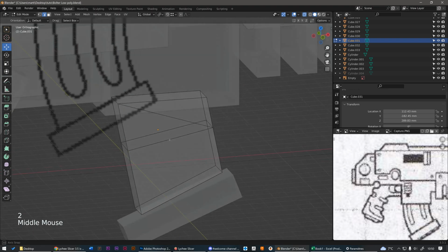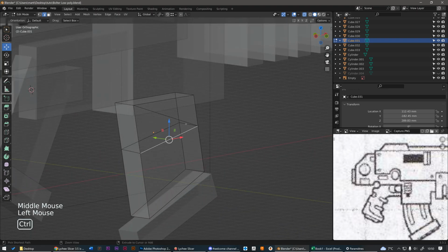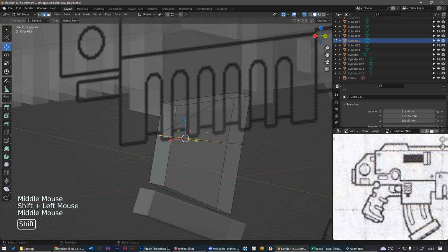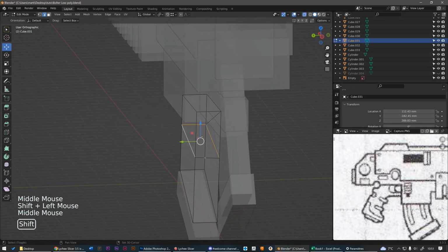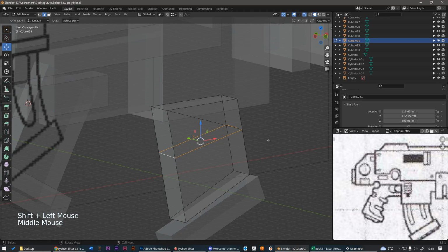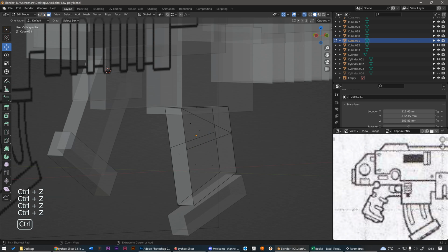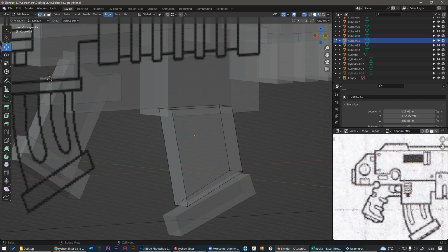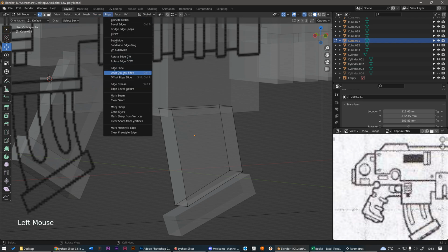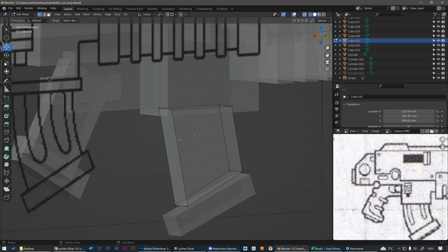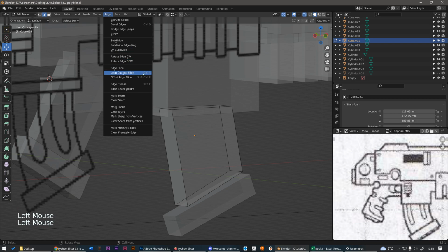An edge loop is a segment which starts at a place, goes all around our object, and goes back here to close the loop like that. To make loops very quickly there is obviously a tool made for that. So I cancel all that. And we'll look for this tool in the edge menu. Since this tool cuts edges, it is located in the edges menu. And here it is called loop cut and slide. So I'm going to switch to edge mode with the 2 key and I use the shortcut for loop cut and slide which is Ctrl R.